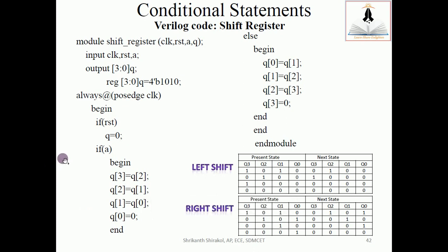So here in the shift register, let me repeat, in the left shift, whenever we feed a value 1010, after the first left shift, this 1 will be shifted and will go out. 0 comes to the MSB, 1 comes to the next to MSB. The same thing is shown here, and the left out bit or the vacant bit will be filled with 0. This decision we can make ourselves, because here I have decided to fill with 0. You can fill it with 1 or anything else. And one more time left shift, this one will take the most significant bit, and one more time, it will be occupied with all zeros.